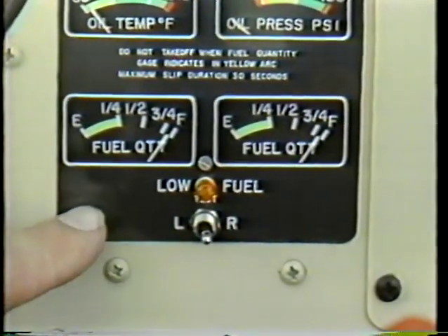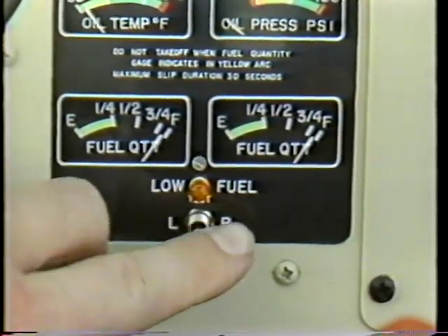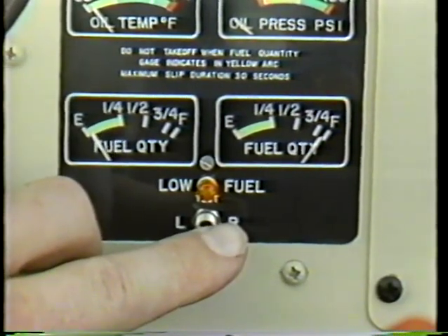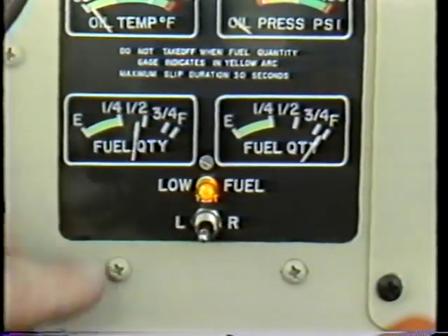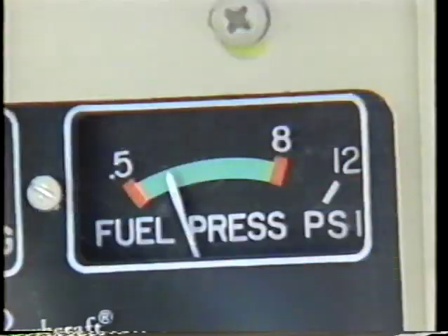The system quantity will be indicated by a fuel quantity indicator system in the cockpit to tell you how much fuel is in each tank. If you find that the fuel quantity indicator is inoperative, you must get it repaired, because this system is required to be operative according to the Federal Aviation Regulations. In some cases, we may have a fuel pressure indicating system and also a fuel warning light that tells us if the fuel pressure is low.